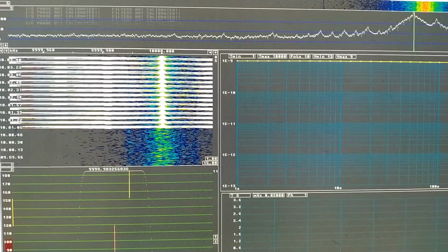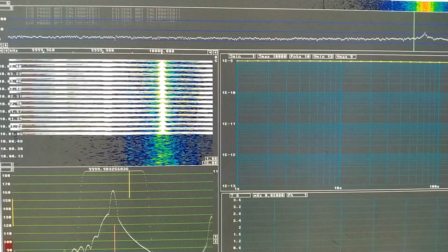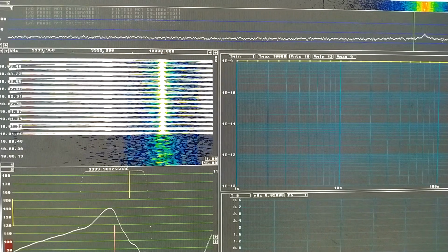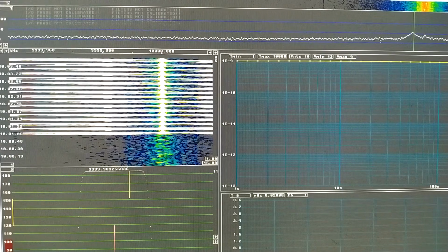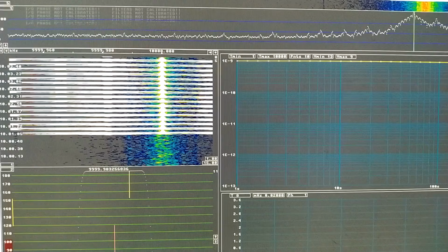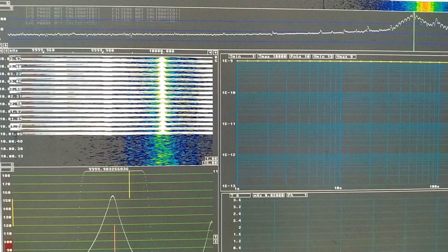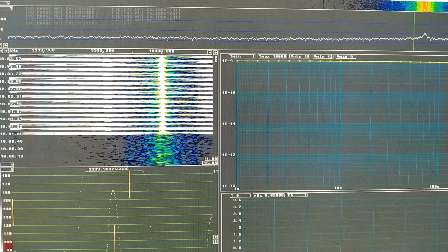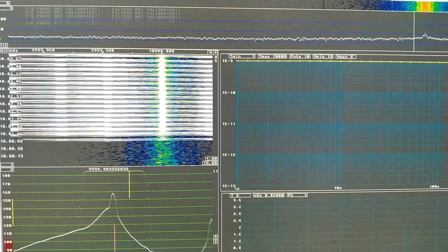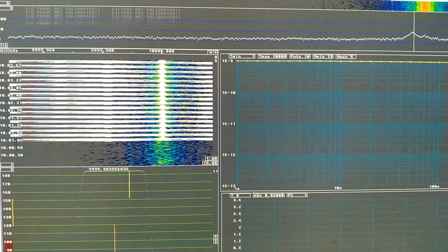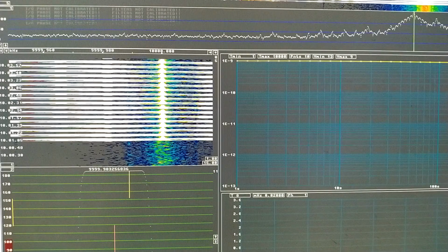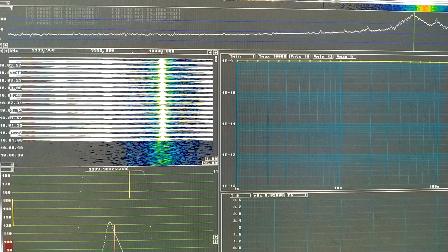And I will disconnect the thermostat and connect it back again once in a while. And this is to force more aging on the crystals. Maybe there is something more that produces noise. There are, after all, 21 crystals, and it's enough if one of them is a little bit bad.